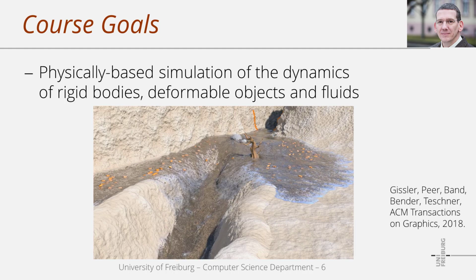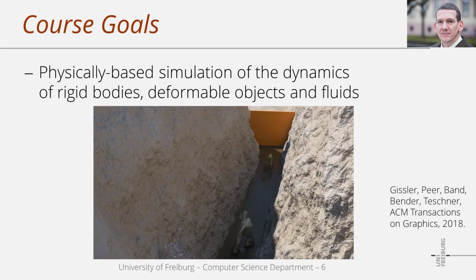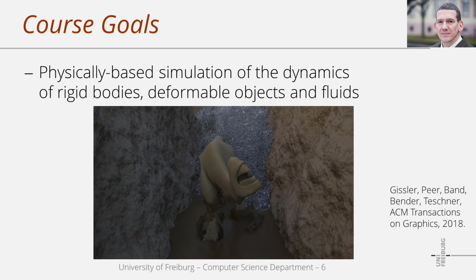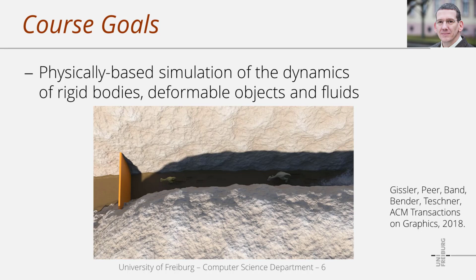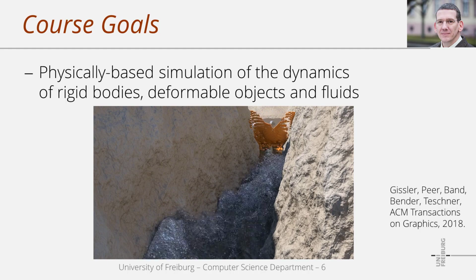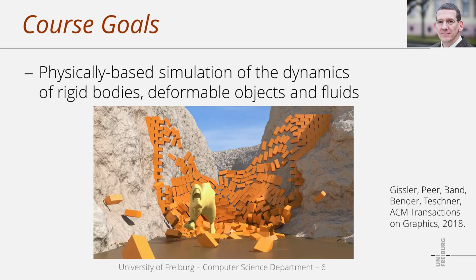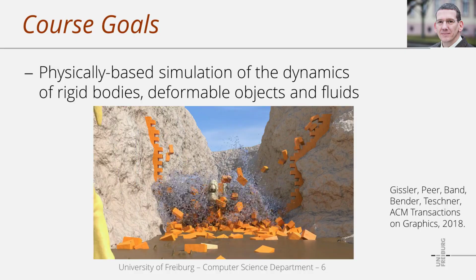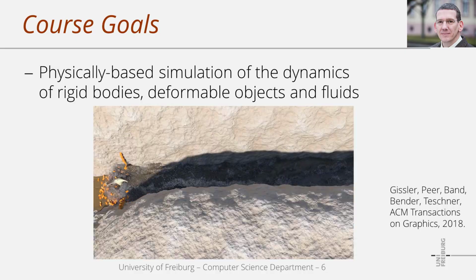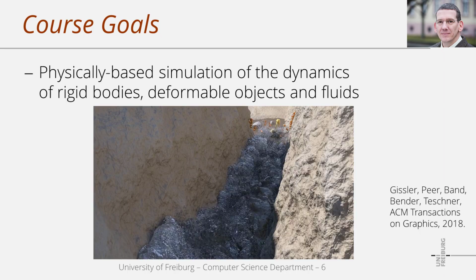Now we constantly compute forces at particles so that we can constantly update positions and velocities, and then finally we end up with a simulation result as shown in the video. In terms of forces, we compute forces that depend on the respective material of a particle. For instance, at fluid particles, we compute a force that preserves the volume of a fluid particle.